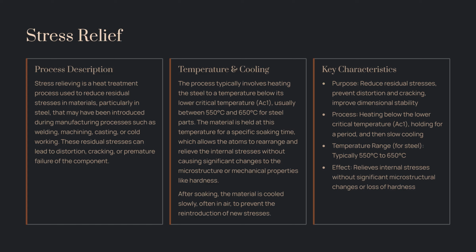Key characteristics: purpose, reduce residual stresses, prevent distortion and cracking, improve dimensional stability. Process: heating below the lower critical temperature, Ac1, holding for a period, and then slow cooling. Recrystallization.